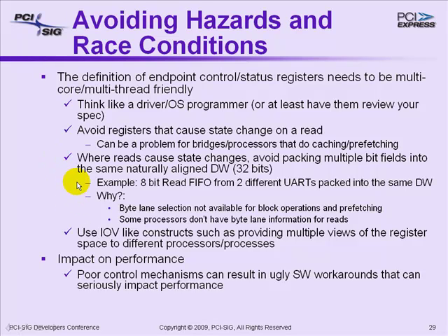Now this is a case where you can't avoid having a read-sensitive device, because here you're going to be reading out of a FIFO, let's say a byte at a time. So you obviously want to avoid having multiple 8-bit registers packed into the same D word.